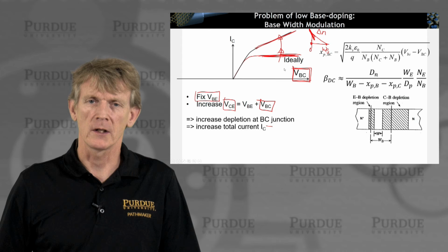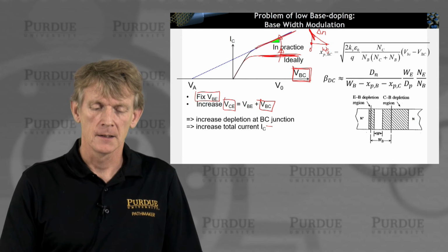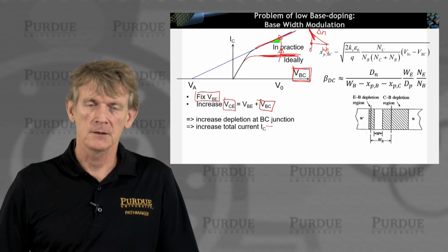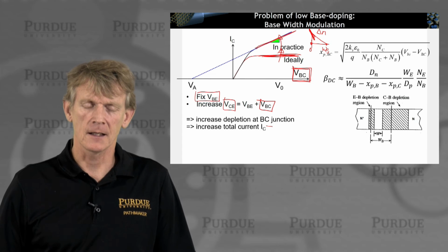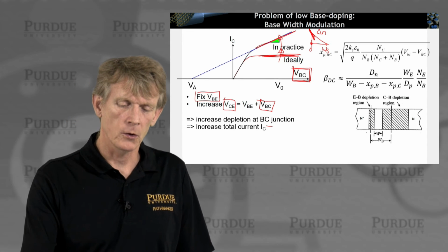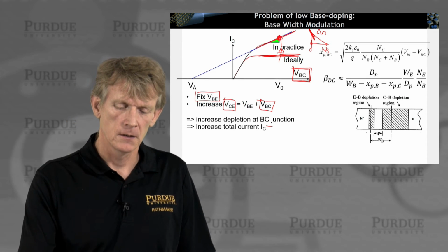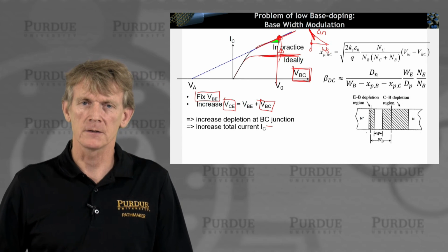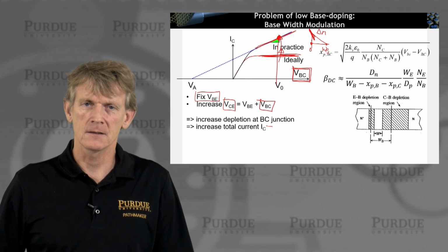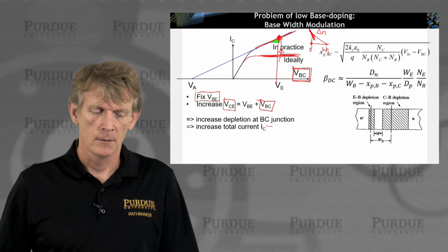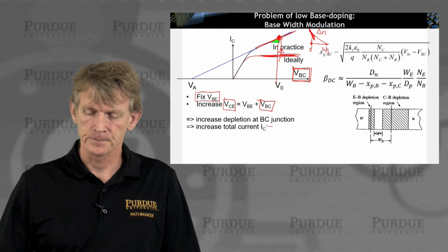This is not an ideal transistor because the output current changes as a function of the base collector voltage. Okay, so what you can do is extend that slope where at your working area, let's say this is your normal working voltage, you can extend that tangent back to negative voltages.